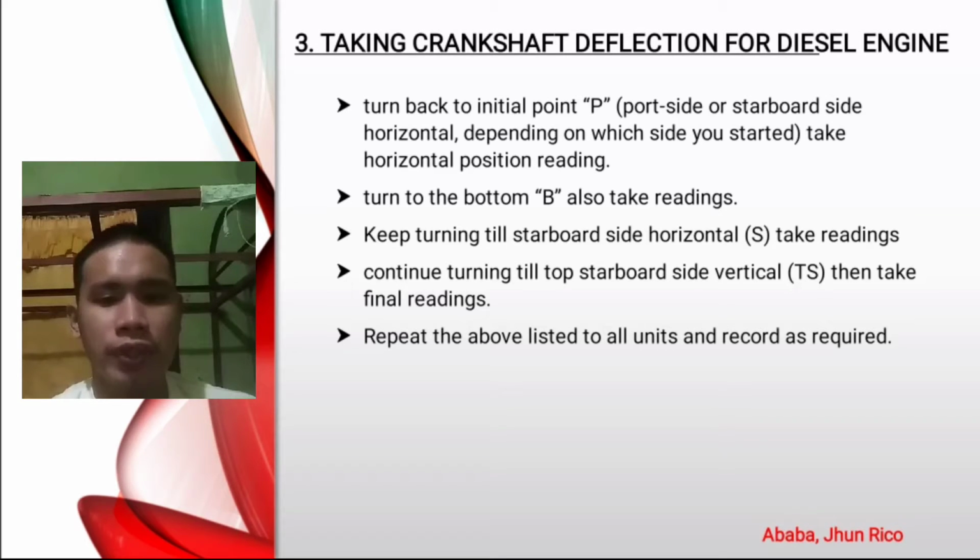Ninth is keep turning till starboard side horizontal. Next is continue turning till top starboard side vertical. Then take the final reading. All of those dimensions, you will just repeat it or record it if it is required.